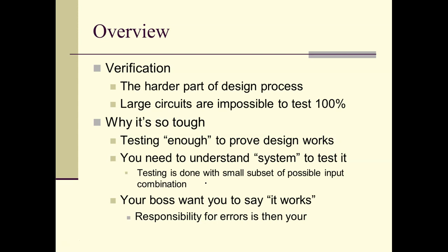Now the issue here is if you have a simple circuit like a half adder, you could test every possible input and check the outputs, verify it's working properly. But when you get a huge circuit, it becomes absolutely impossible to test every single input. Particularly if you have a circuit with 20 inputs, right there you're at 2 to the 20th. You've got a lot of inputs. It's going to take a long time. You don't do it. And so it's really tough to verify a circuit for a couple of reasons.